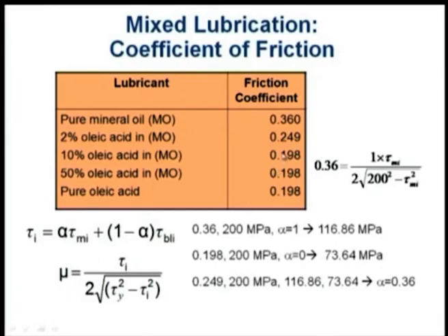That means if the coefficient of friction is something like 0.2469, I can figure out the metal to metal contact. It says that 36% of asperities are directly in metal to metal contact. There is no boundary additive lubricant on those, or maybe it is depleted, boundary additives have reduced, or more boundary additives can be added.